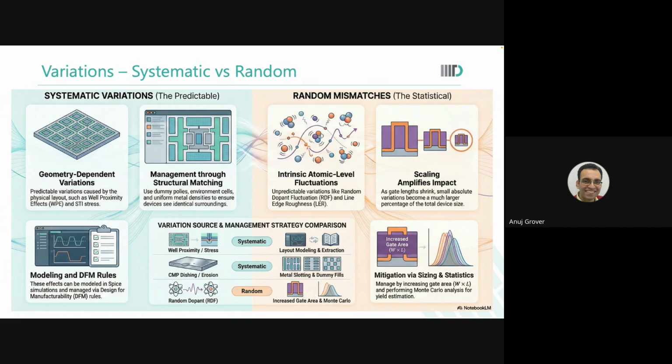Now, you are talking about the stress effect because of STI only. But in advanced technologies, we also use very different kinds of stressors. Even on the gate, we use stressors. So I would not want to explain why, like this observation that when it is STI, this happens and that happens. Stress effect can be used to boost performance. And it is actually used to boost performance in a very significant way in advanced technologies.